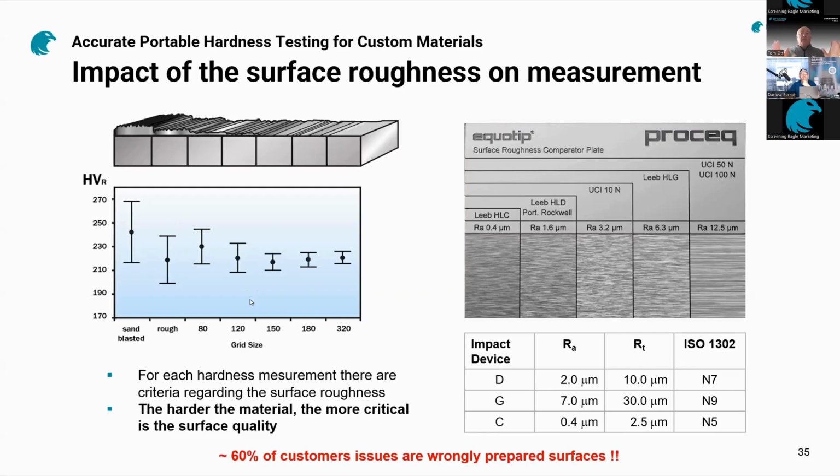If you have a very high range, that's an indication that your surface preparation might be inadequate. A high range indicates one of two things: either a non-homogeneous material or inadequate surface preparation. So, provided you've already established that you have a homogeneous specimen under test, that high range is from your inadequate surface preparation.